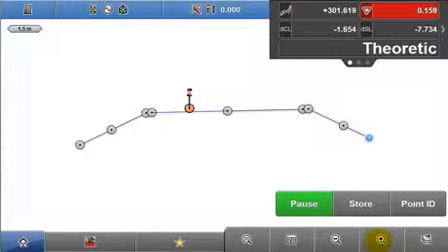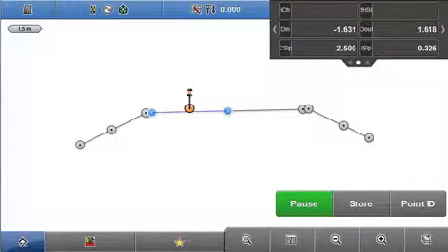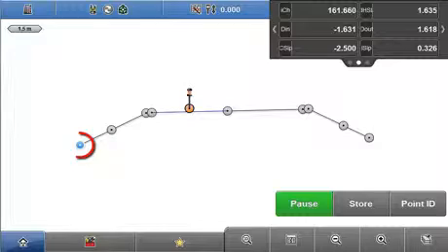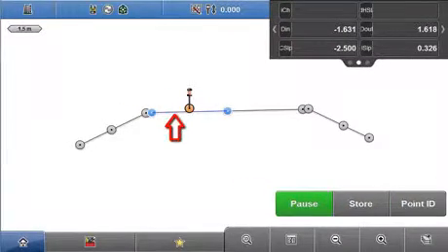Whilst in cross-section view, it's also possible to select a cross-slope to stake out by tapping it. The values in the info panel are explained in the roading info panel video. To select a string line whilst in cross-section view, tap the point that represents the relevant string line. So there are 2 stakeout possibilities: stakeout relative to a specific string line, or directly stake out a cross-slope element.